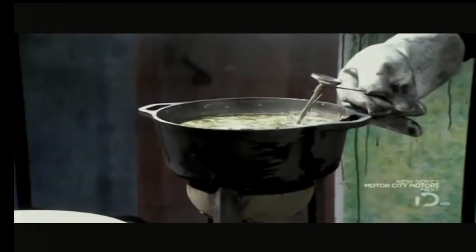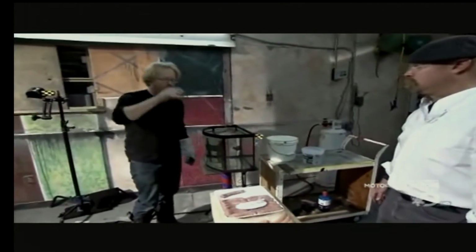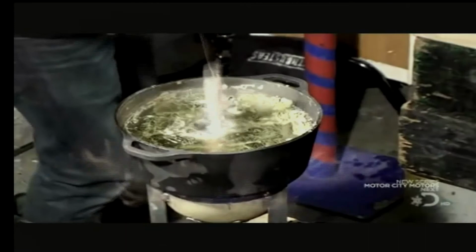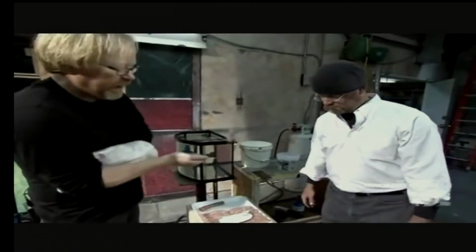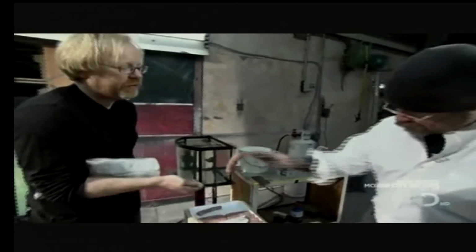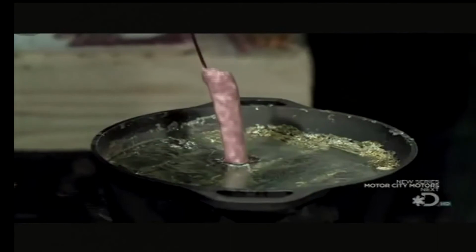We're not ready to put our hands in there yet, but we hear that if we get the lead 200 degrees over its melting point, great, that's 850, let's try it. It'll stop sticking. Here's that finger, bucket of water. Shake it off into the lead. And it looks pretty much perfect, and it's still cold. So 850 degrees Fahrenheit is the magic number.